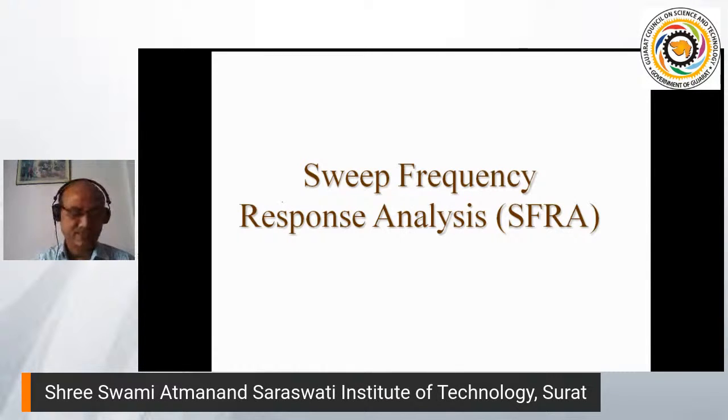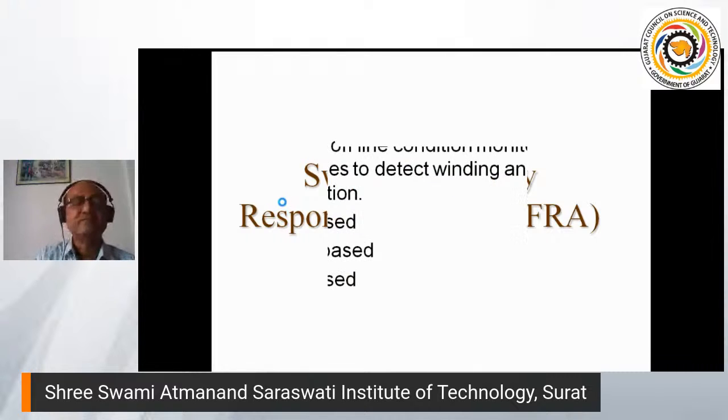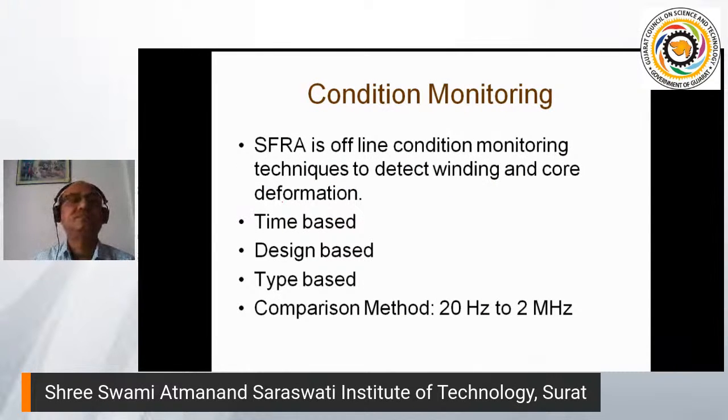PD can be done for other electrical equipment also, but sweep frequency response analysis is done for a transformer. This is also a condition monitoring technique. It is an offline technique. PD measurement can be done online or offline both. Acoustic and UHF can be done online. Electrical method has to be offline.